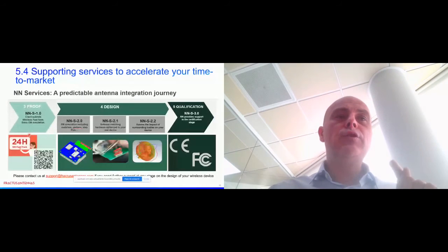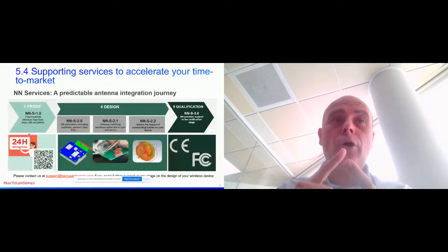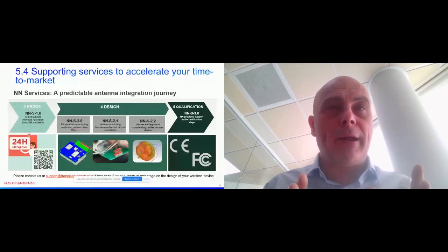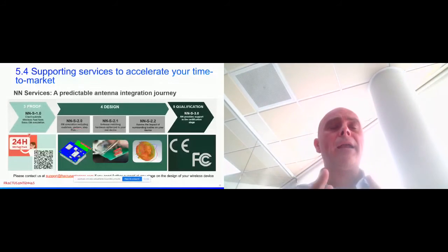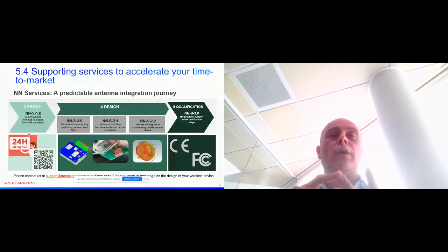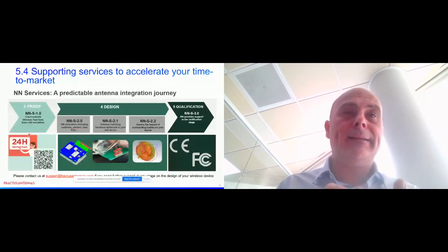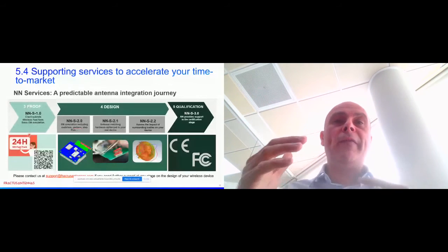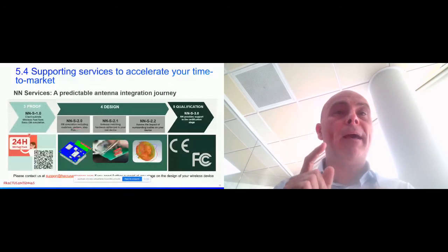So precisely, this Wireless Fast Track service requests from you only the PCB size and the frequency bands you are going to operate, if it's LoRa or you want to combine with other radios. And in return, we tell you which is the best antenna booster. We tell you the bill of materials for the matching network, an estimation of the performance in terms of S11 and efficiency, and also recommendations on how you should shape your PCB in order to get the best of it.